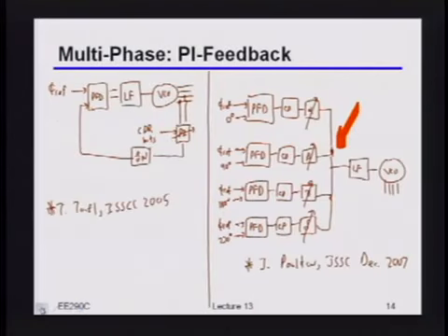Can you do the tap control by changing the current for this case? The charge... what do you mean, control? Tap control? I mean the alpha, beta, gamma, and delta. Oh, yeah, absolutely. In practice, what you really do is just adjust the currents in the charge pump, or in fact, you may even tweak the currents in the charge pump or have some switches and then just have two charge pumps with adjustable currents. Lots of ways you can build this.